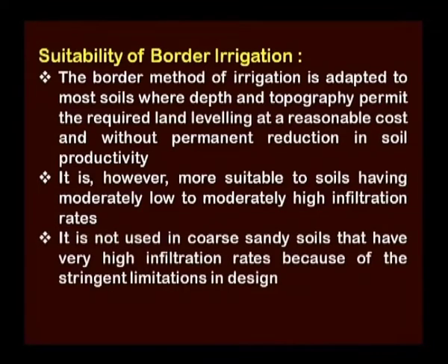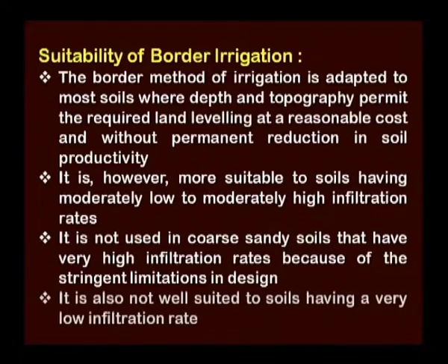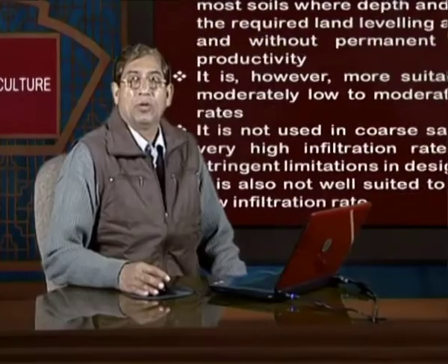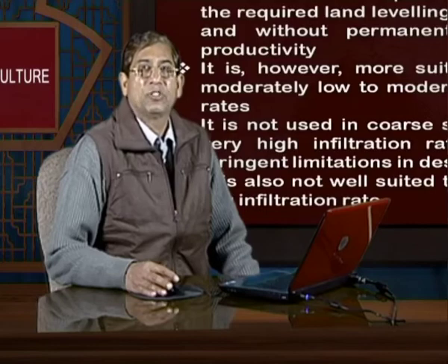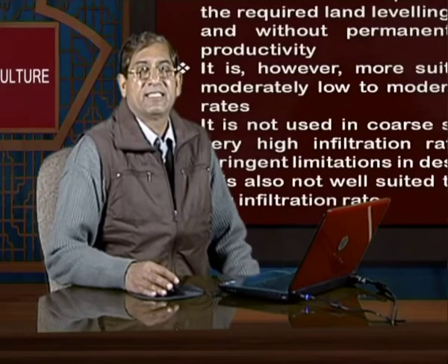It is not used in coarse sandy soils that have very high infiltration rates because of the stringent limitations in design. It is also not well suited to soils having a very low infiltration rate. Generally, in medium textured soils and in areas where the stream size is higher, under those conditions border irrigation is suitable.